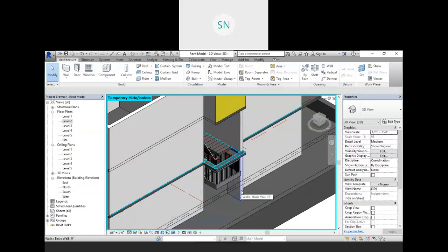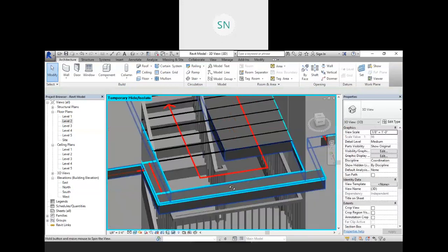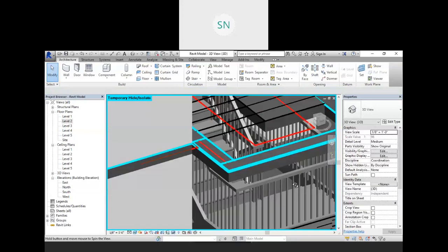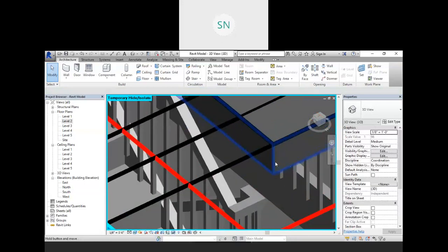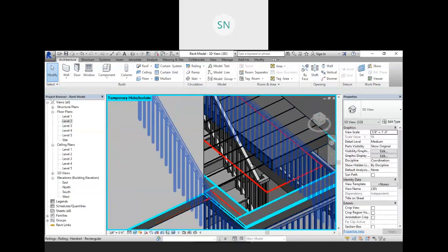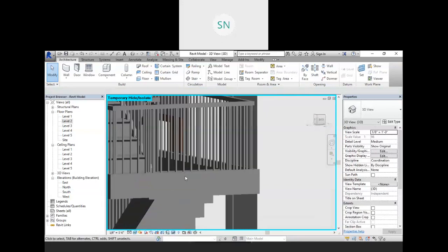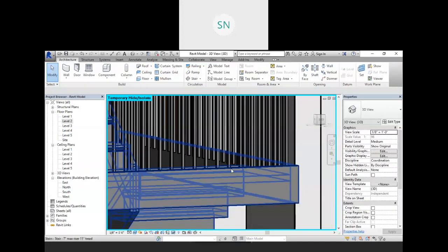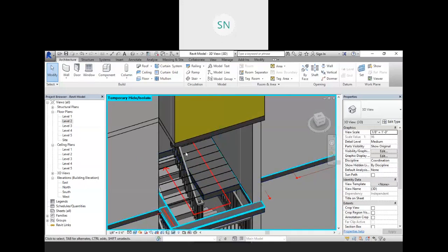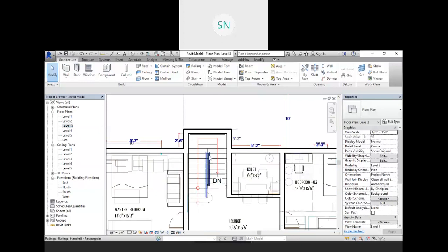Okay, now make sure that you have a proper wall cut over here. See, there are many chances that our head is going to intersect with this roof because we have a lot of height over here, right? So what we need to do, we need to reduce this, we need to edit this floor on level 3.